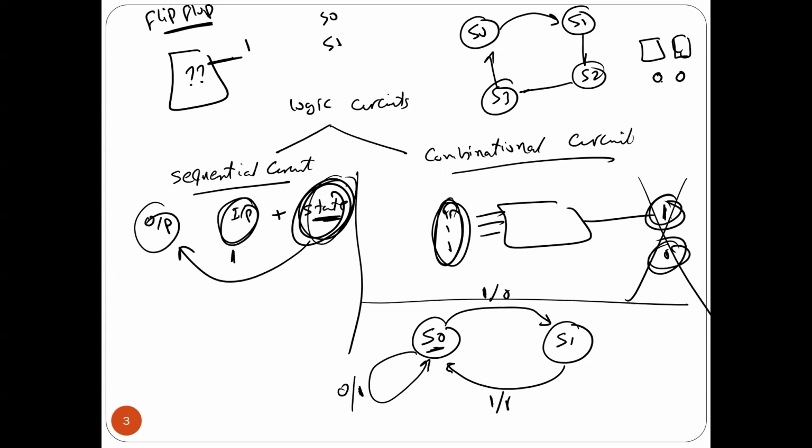So if the 2 flip-flops are storing 0, 0, so actually I'm in state 0. If it's storing number 1, so I'm in state 1. If they're storing number 2, so I'm in state 2. If they're storing number 3, I'm in state 3. And so on. You got what I'm saying? So anyway, you will understand better as I teach you more, but for now, we should understand sequential circuit is different from combinational circuit. In sequential circuit, I have to use flip-flop to make states. Okay? And the system should change state from time to time, as I'm going to explain. You change the states. Okay?